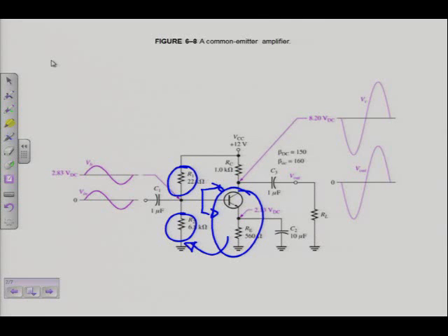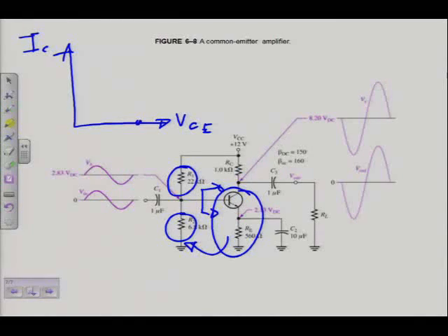Why am I so serious about getting the voltage that I should? Because the first thing that we've learned is the transistor's characteristic curve, IC versus VCE. I've got my load line, and we saw that if I want to bias using R1, R2 to get my Q point in the middle of the load line there.